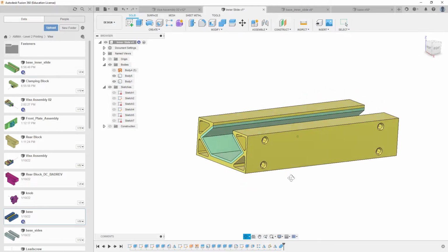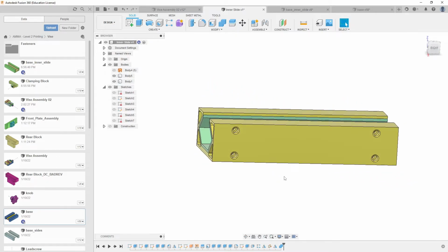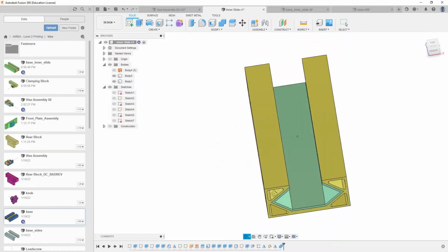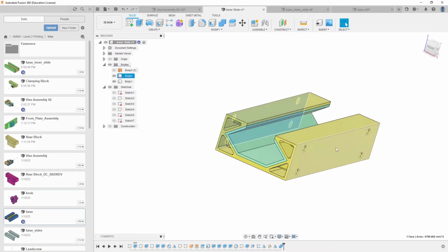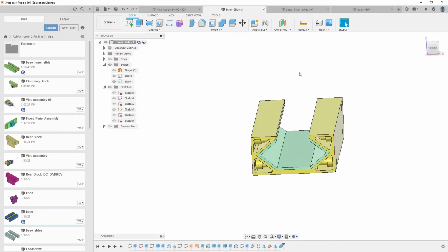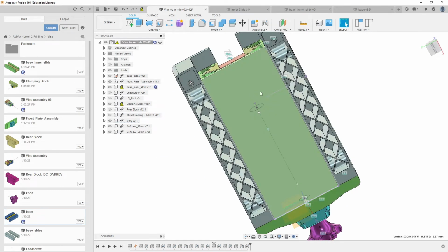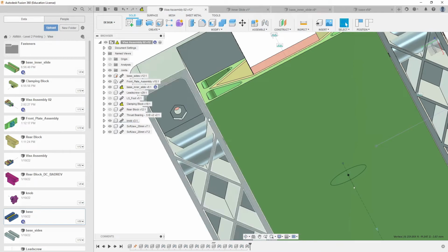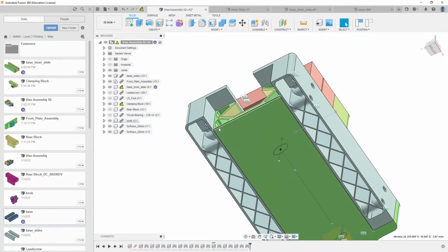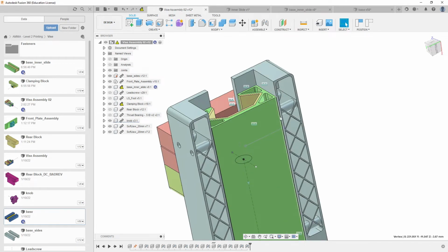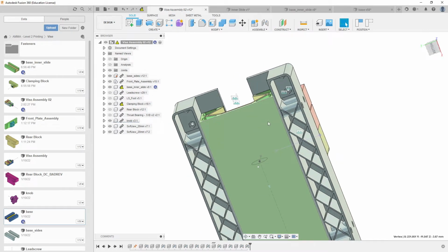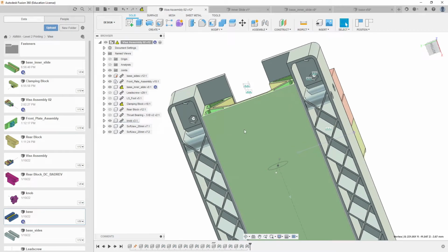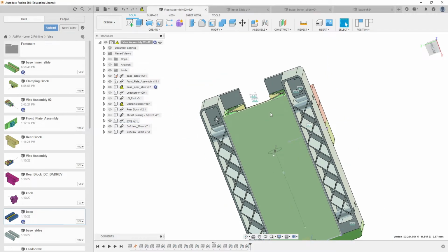So this particular piece right here, I mentioned that we need to reduce some sides. We need to make the thickness from this edge right here, you know, this face over on this side to this face, we need to reduce it a little bit to fit within these boundaries right here, because it's by default just sliced away. You know, the distance from this blue wall is what we did. This one to this one over here, 75, I believe it was, is going to be too tight. So if we give it, you know, 1/4 of a millimeter either side, even something like that, maybe 1/2 millimeter, I think 1/4 millimeter would be fine, then we're going to be a lot better. It's not going to have to be wedged in place.